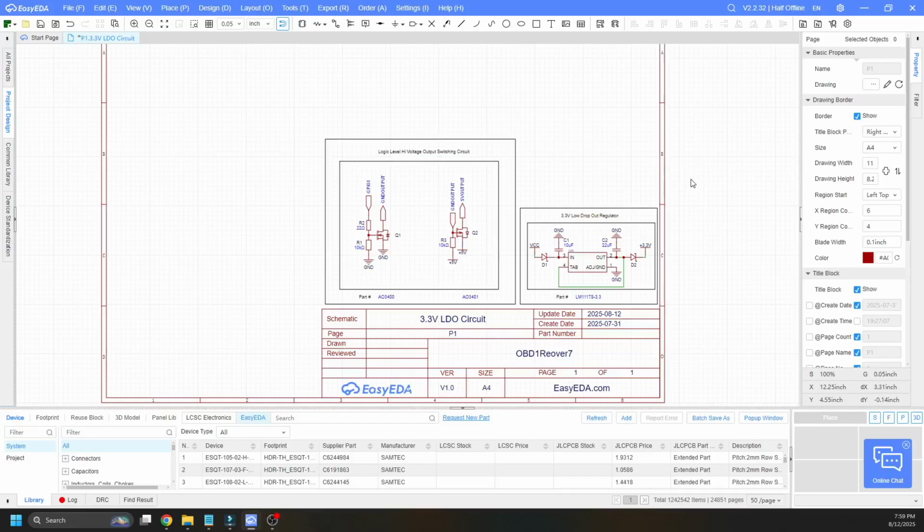You're going to be getting a little bit more comfortable now, hopefully, with building out some circuits. And this is a lot cleaner way to do this. It doesn't have wires going everywhere. When I say wire, if we look over at our dropout regulator, you can see there's a wire between tab and the output, because these are both actually outputs. They need to be linked to each other. So that's a wire. You can always use a wire if you want, but I personally just find it cleaner to use ports like this, especially when you start building big schematics. It just makes a lot of sense.